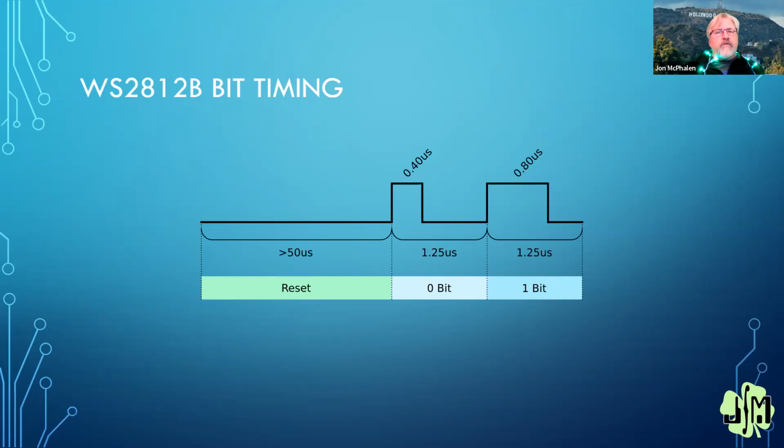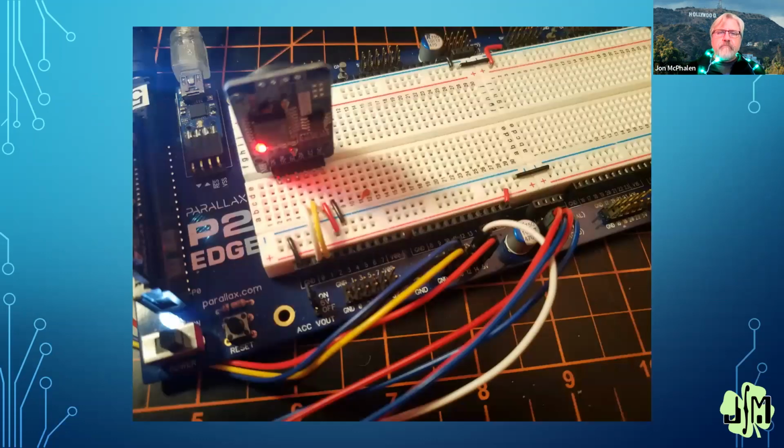But again, if you say be red, it will be green and vice versa because of the byte order the chip is expecting. John, that must explain my red and green being switched in your demo, huh? Yes, but we were talking about that and then got cut off. Yes, that's exactly why. So if it wants to be red and it's green, change the driver.